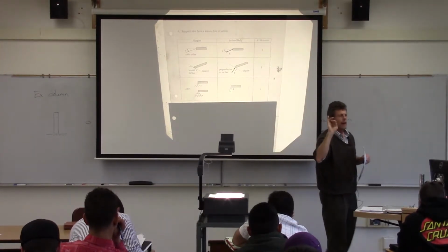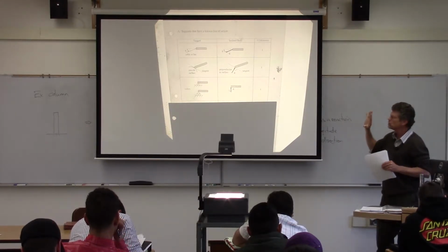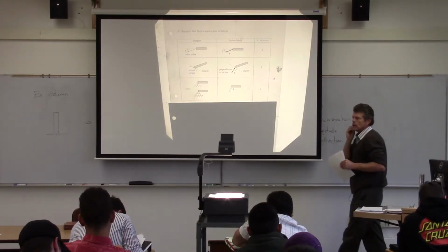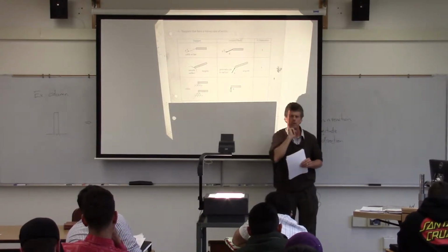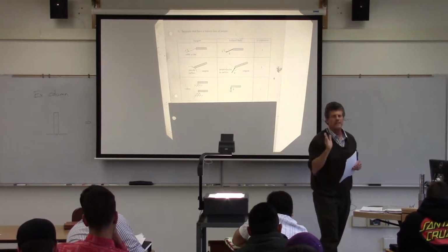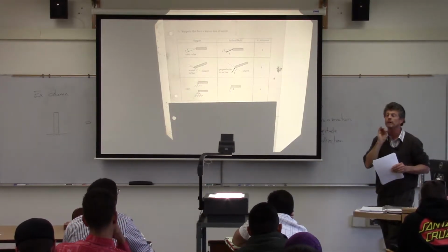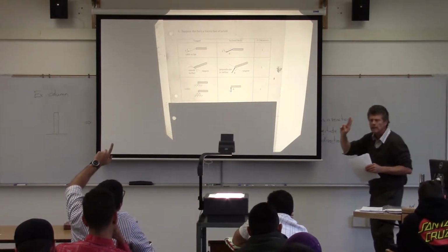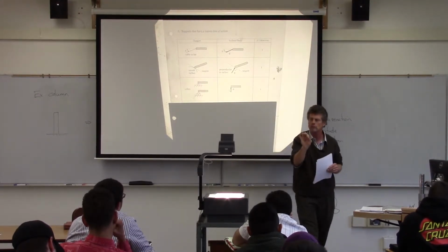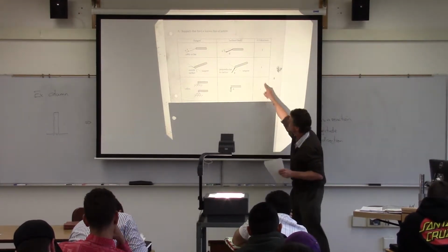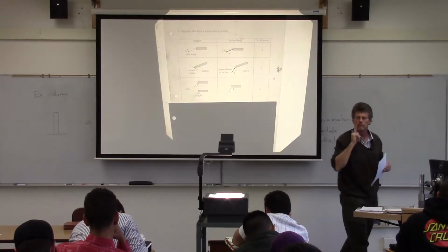Now, the one thing I'll add, and just think about this when you get into EIT exams, we like to think of it in terms of rollers. It makes sense that the force can only be that way, but it could be the other way in some exams. So be very careful with that at EITs. But the key thing is its direction is known. It's perpendicular to that surface, once again. So the only unknown is its magnitude.